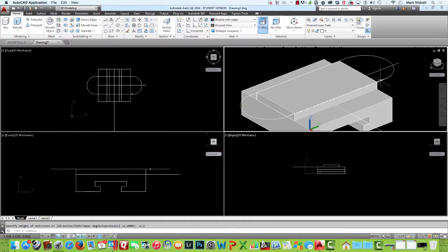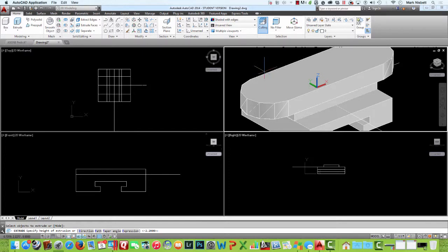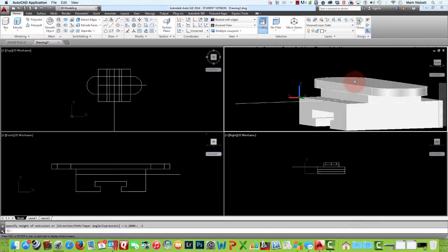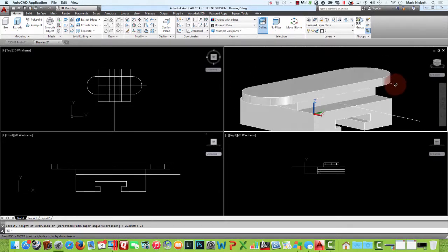And then this shape up here, we can convert that into a polyline and extrude that up. So I'll use P-edit, and I'll pick this, turn it into a polyline, hit J for join. We'll pick this line, and this arc. Okay, and that's now a polyline that we can now extrude up 0.3. All right. So now we have our little base plate done. So we can see that looks like that.